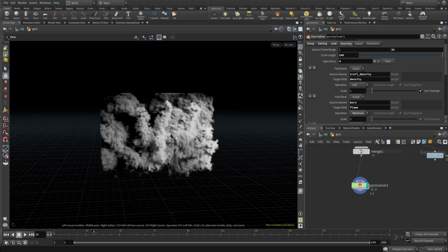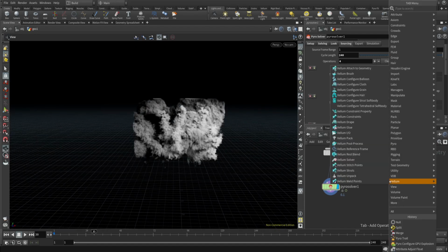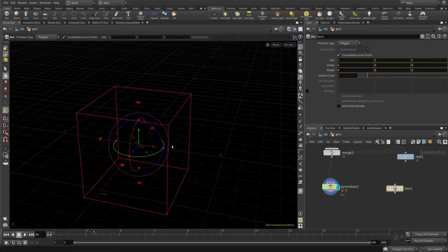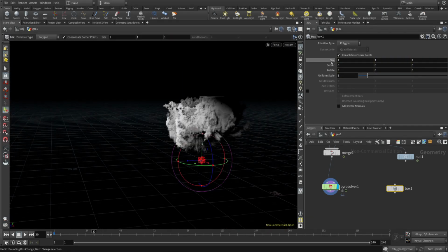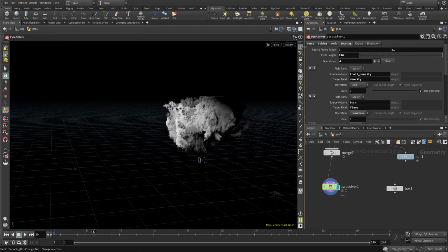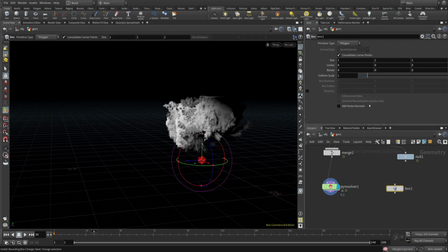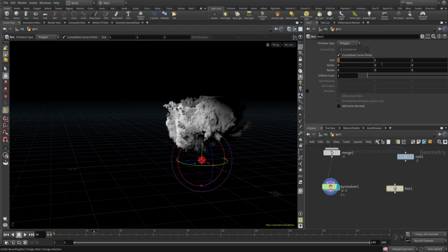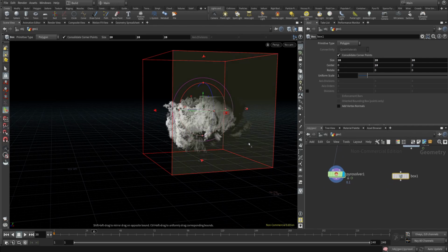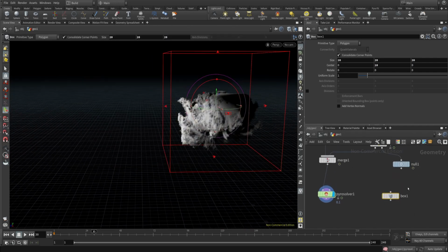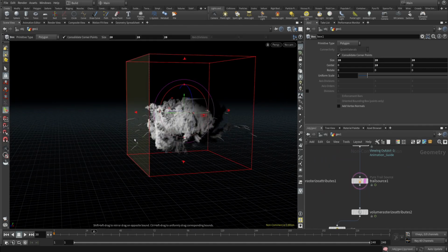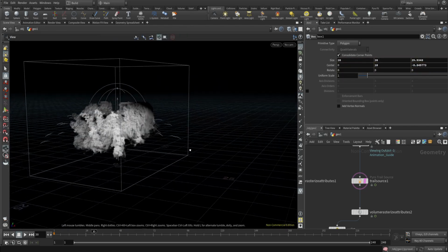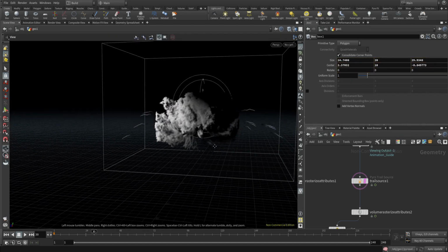Working very well, but we definitely need to extend our container size. As I mentioned before, again, I'm going to use simple box because it's giving me some handles in the viewport to control its size. So you just need to connect the size to the max size, space relative references, and same for center. Let's keep going with 20, 20, 20, and 10. Set this size based on your trail points. We need to extend it at this side and this side. Okay, something like that.